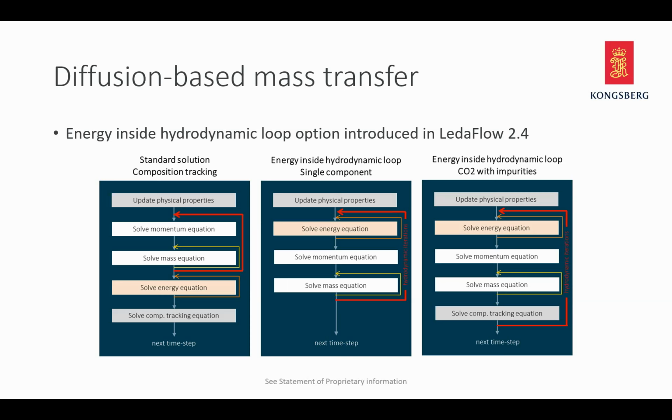The hydrodynamic loop is represented by a red arrow here. For single components, we have introduced, as I said, in LedaFlow 2.4, this energy inside hydrodynamic loop option, which means that we solve the energy equation together with the mass equation and momentum equation.